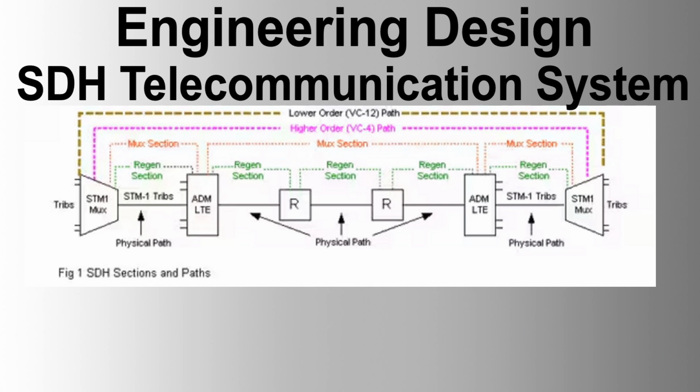System spare capacity and spares. Hardware spare capacity. 20% spare capacity on interface I/O cards, wired and terminated, ready to configure and use. 15% spares supplied for cards, terminations, and physical slots available for use, but not installed.